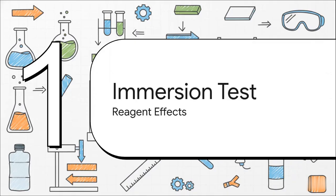All right, we are pivoting to Unit 4, Analytical Tests. Section 4, the Water Absorption Test, governed by ASTM Standard D570. This is absolutely critical because plastics used in humid or wet environments naturally absorb water over time, and this absorbed moisture drastically degrades both their electrical and mechanical properties.